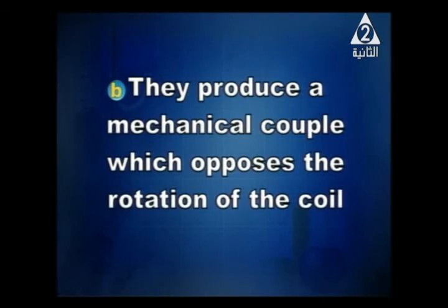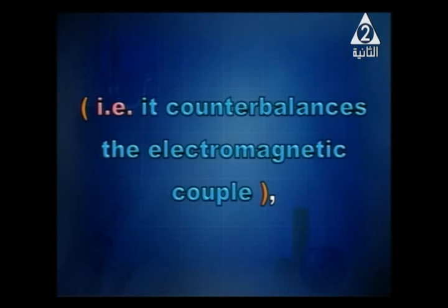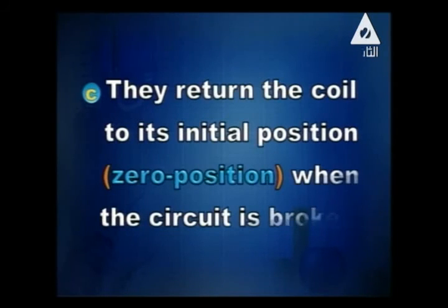They produce a mechanical couple which opposes the rotation of the coil and counterbalances the electromagnetic couple. Also, hair springs return the coil to its initial position, to the 0 position, when the circuit is broken.